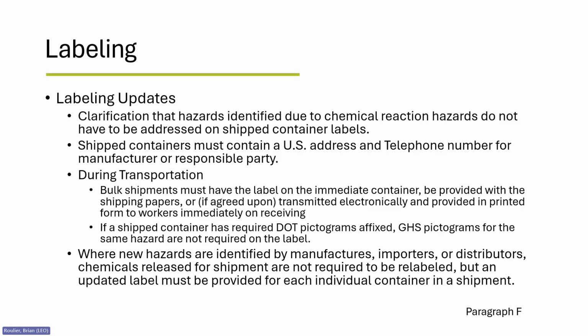Where manufacturers identify a hazard not previously known, which affects the shipped container label, they are not required to relabel any containers considered as released for shipment. However, they must provide an updated label to the receiver for each chemical, and end users must apply the new labels prior to introducing these chemicals into the workplace.